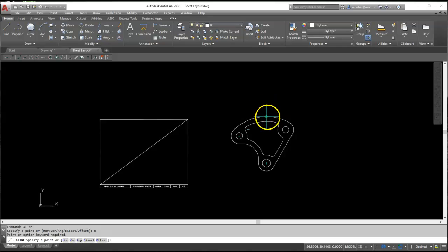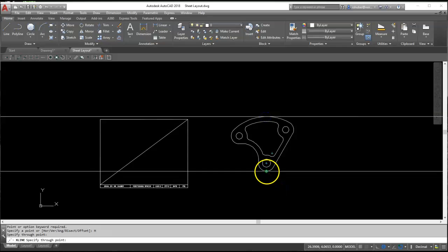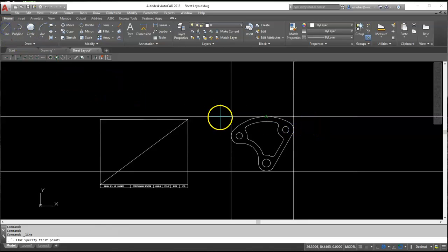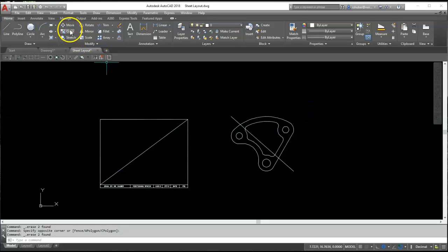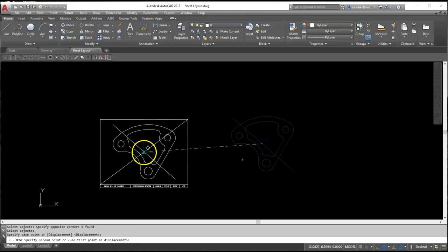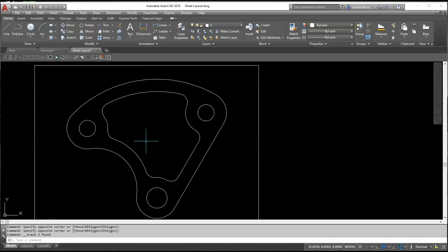Horizontal X line. Let's put 2 going there. Spacebar, repeat last command. Do verticals, 2 verticals. I'm going to draw a line on a diagonal here, and that'll be the center point. So I'll go ahead and delete these lines. Go to Move. Put them in place. Go ahead and delete these lines.